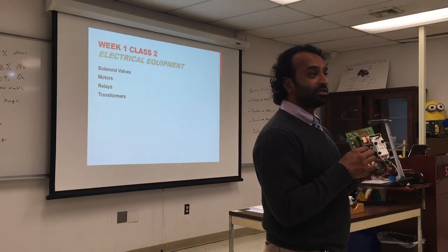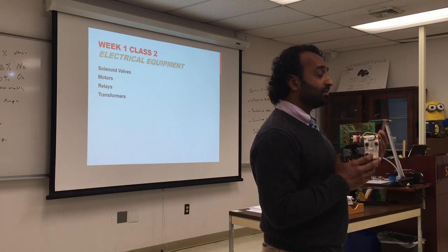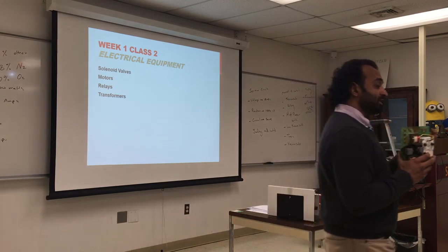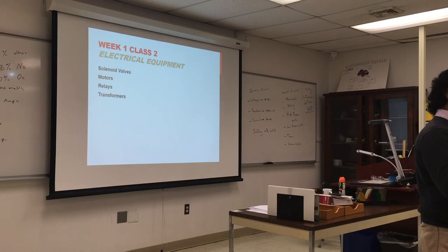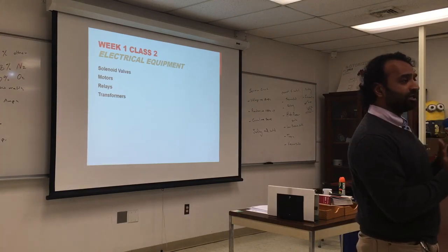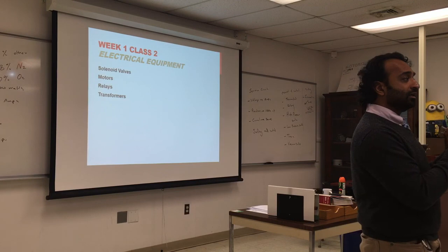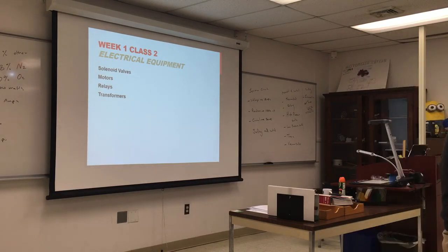If we look here, we have two relays. One of them will engage. The relay has an input, right? This is the sensor, which is inside the tank. It senses the temperature. Once the temperature is within those two limits, it will close the circuit and engage this relay. This relay will tell the connection here for the burner to turn on or off. So the relay has an input and closes a circuit.